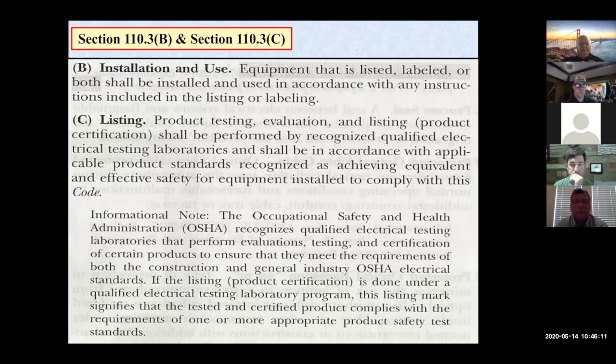And the manufacturer puts this out at the factory and it has to be listed, or tested by a recognized testing laboratory, and the label stamp put on it, and that makes it legal to be put in the code. I want you to know, if you don't have the listing, if you don't have that label, you know what I'm talking about, that somebody made out in his garage or whatever, it is not legal by code. And here's the code, like it or not. Well, I built that at home. Well, you've done a great job, but where's your stamp? Well, I don't do that, I just made it. Well, okay, that's your business.